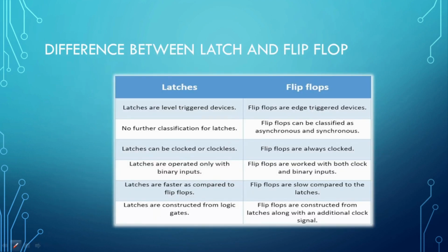This is the difference between latches and flip-flops. Latches are level triggered devices and flip-flops are edge triggered devices. There is no classification in latches, but flip-flops are classified into asynchronous and synchronous. Latches can be clocked or clockless, but the use of a clock is necessary in a flip-flop.